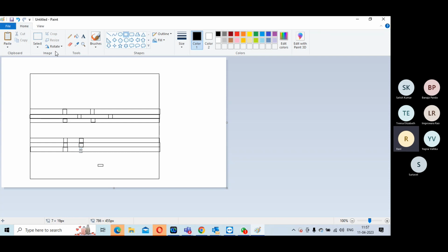There's an equivalent. Some standard cell logic like NAND gates can be constructed without altering the physical nature of the base layers. Just with the wiring, with the metal changes, that filler can be converted to create a NAND gate or AND gate.